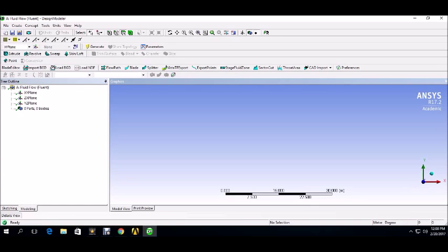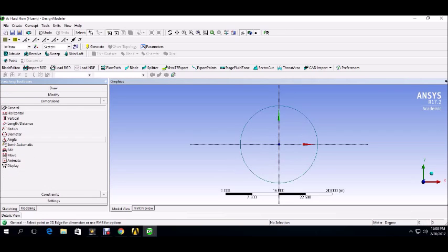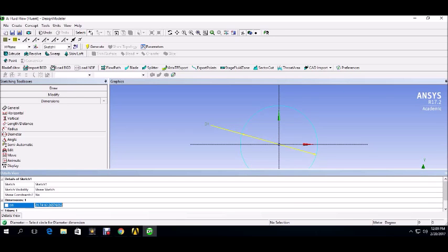So to start, click this Z so we can be in the XY plane. Click XY plane, click new sketch. Go to sketching tabs, click circle. Make sure down here you're at 0, 0. Once you're at 0, 0, make the first circle, end it wherever you want. Give it dimensions, diameter. Make the circle 1 meter in diameter.